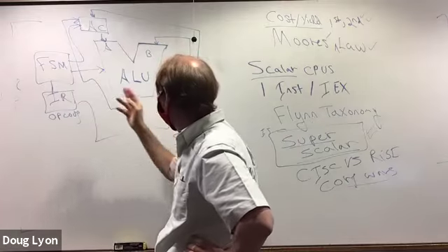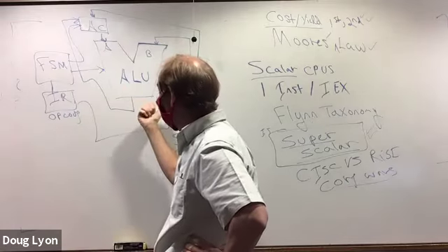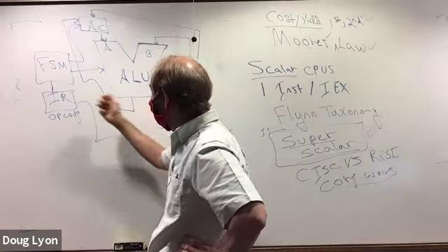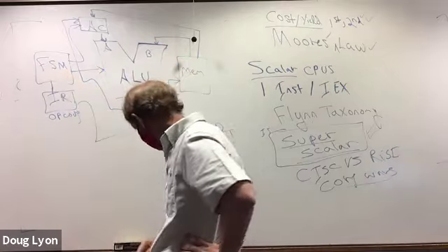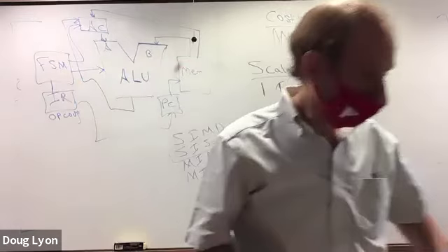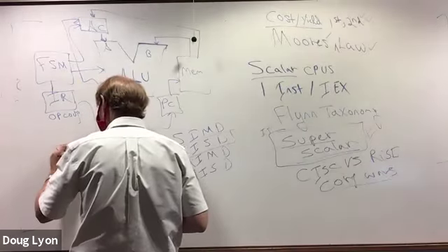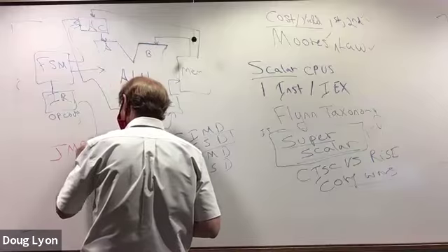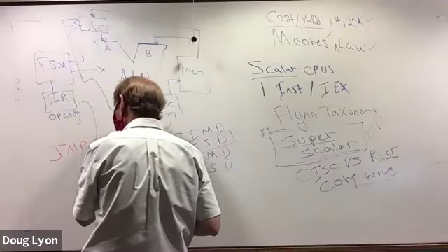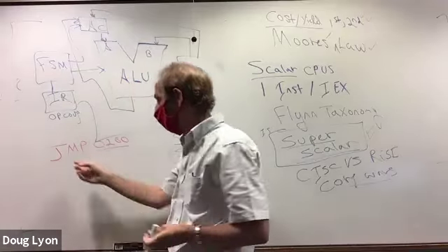The program counter may have to be jam loaded with another address if the finite state machine sees an instruction that says something like jump to address 0200. Jump is like a go-to.